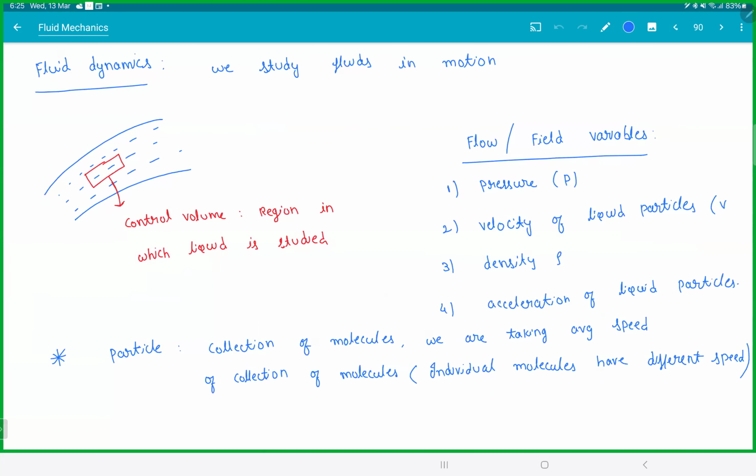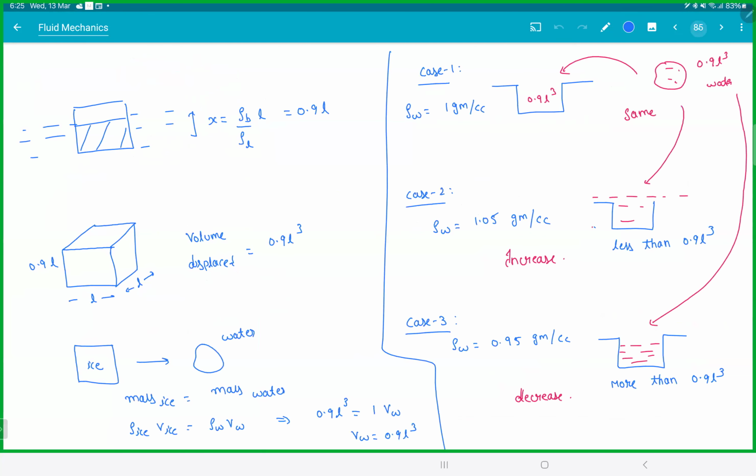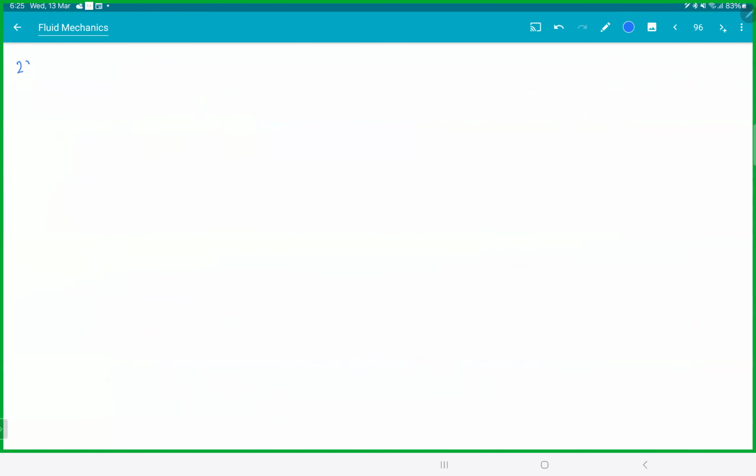You try. Let's say velocity v bar is a plus bx i cap minus by j cap. So this is the velocity of a particle on a streamline. A and b are constants. Find the equation of streamline and approximately try to draw the path.